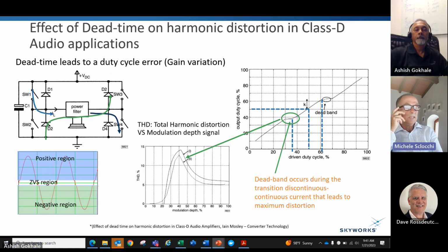The last question I would like to ask you is, we know that the main advantage of GaN, you get it at high switching frequency. GaN can switch at high switching frequency while keeping very good performance and efficiency. Typically, they try to go into the megahertz range or even above, right? And most of the drivers today are specified at 500 kilohertz. Is there really a limitation for the driver, or can we go higher than what usually is specified in the data sheet?